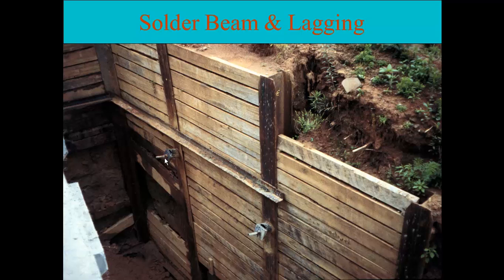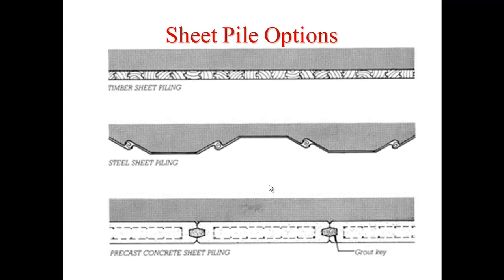We've also noticed that they've got these threaded rods. These are called tiebacks that get driven into the soil and anchored to a point where they'll actually hold the wall in place, even with these driven piles down there, just as an additional. And then it has these rakers or crosslot pieces that will tie everything together, and these just get welded in place temporarily. Sheet piling options could be timber sheet piling,